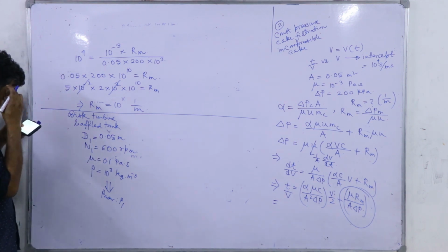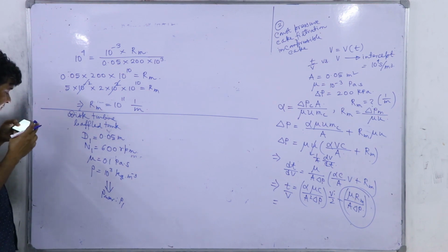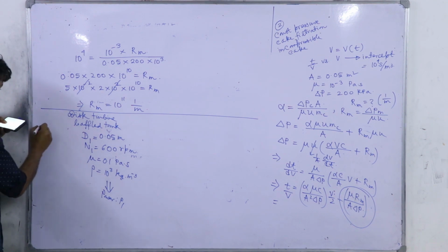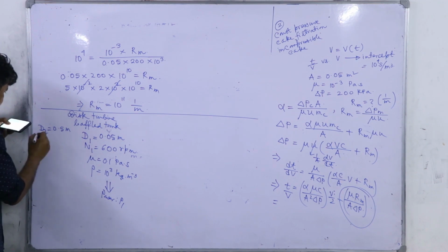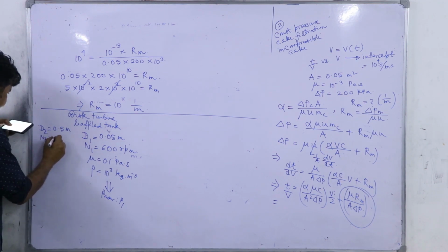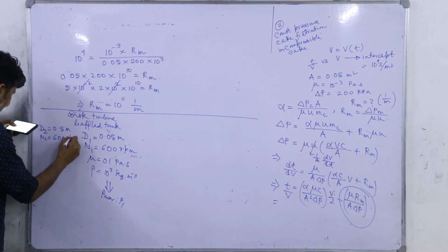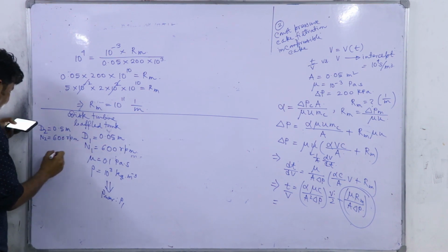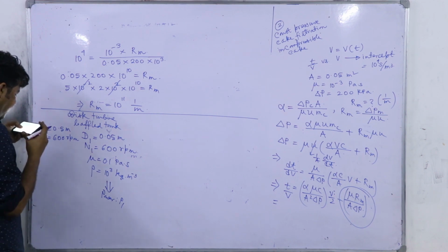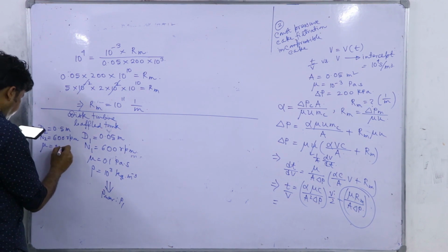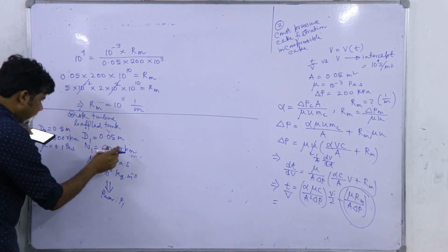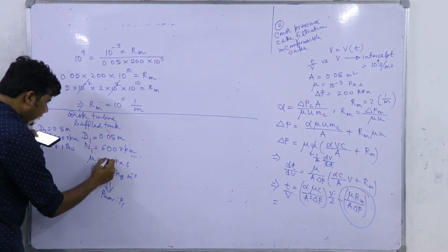Here the 600 rpm, 0.001 Pascal second viscosity and liquid density are given. The actual application has a turbine diameter, d2, of 0.5 meter. This is simply a scale up problem. Impeller speed n2 is 600 rpm. Yeah, in both cases the impeller speed is the same. Liquid viscosity and density: here the viscosity changes to 0.1 Pascal second, so previously it was 10 to the power minus 3.